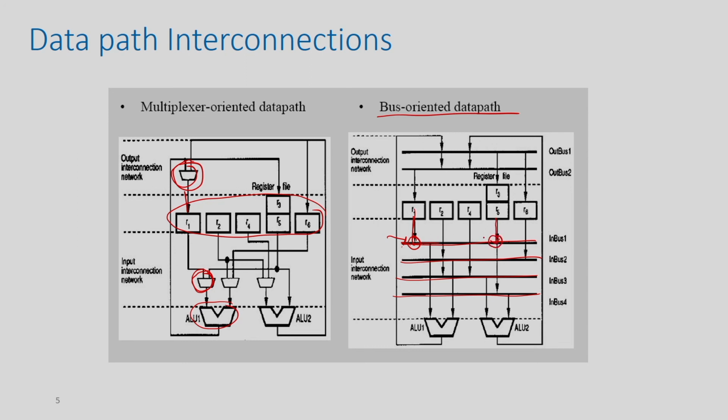So, that means if I put this value 0 and this is 1, then the R5 value will come to bus 1, right. If I put this is 0, this is 1, then this R1 value will come to this bus. Okay. So, you cannot put more than one at a time step, then it is a race condition. There are two data coming to the same bus, so it will be an unstable situation, right. So, in a control step only one of the inputs can give the data.